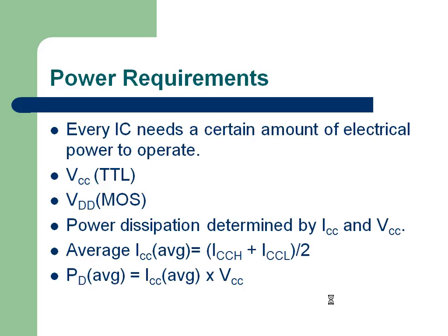Not only that, in many other future calculations also, let us take a 3-input gate. How many input combinations will be there? 8 combinations: 0 0 0, 0 0 1, 0 1 0 and so on. Now the question comes, what is the chance of having the 0 0 1 input combination? If we don't know anything, we assume all are equally probable, that is, unbiased inputs. Then we assume 12.5%, how? 100 by 8. 12.5% of the time, the input is likely to be 0 0 1. Let us assume for each combination we have a different amount of power. Then we take the average and solve.